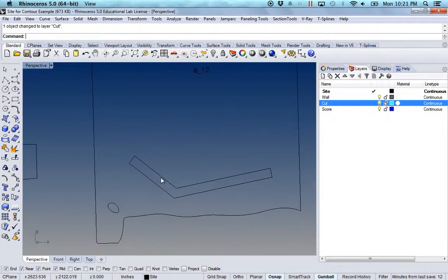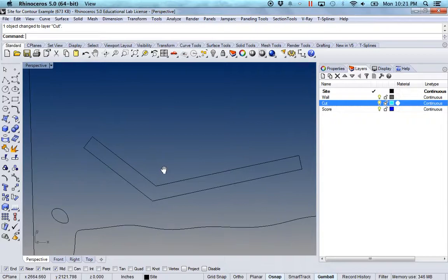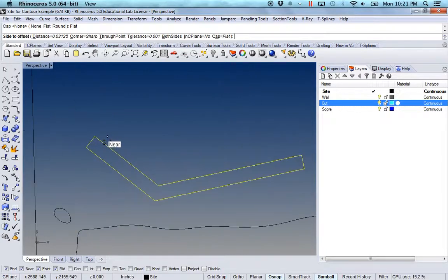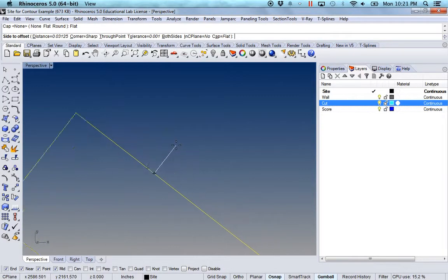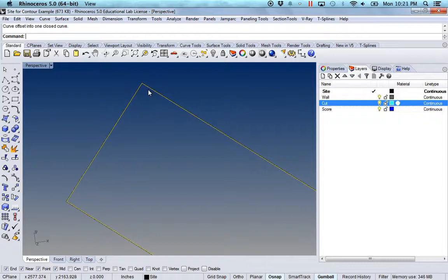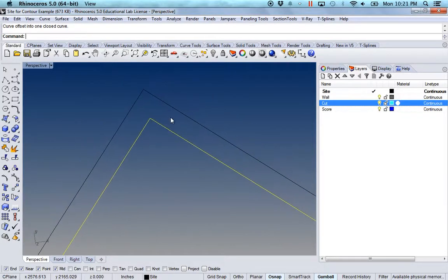One way of doing this, and it's not the easiest, just one way, is, say for example, this is the wall where the wall's going to slide in. I can do offset, cap flat. I can offset it some distance, right? You know, a 32nd of an inch or 16th of an inch, depending on what scale you're working in. You don't want too much tolerance, or else when you put your model in there, it's just going to wiggle around in there. You put in some distance. So again, that's my offset.